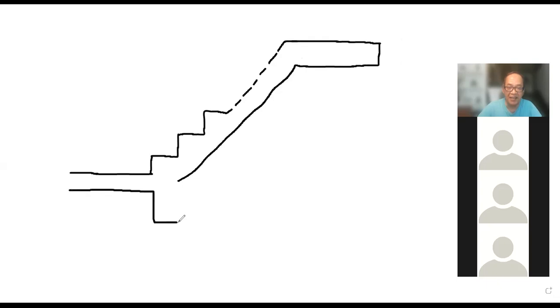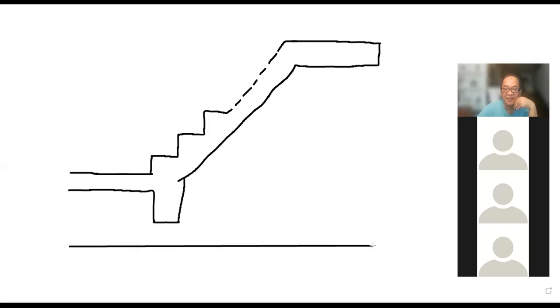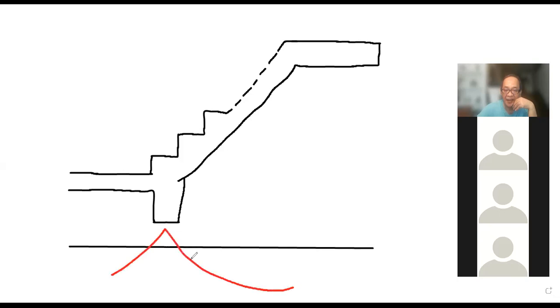Even though we did not design the staircase, but basically the detailing for the staircase, because our bending moment, remember kita punya schematic for the staircase, okay, is something macam ni, and we had apa nama negative bending moment di sini, and a zero bending moment di sini. So the negative bending moment, we need top reinforcement. Therefore, untuk top reinforcement, I'm using yang ini. This will now be my top reinforcement.